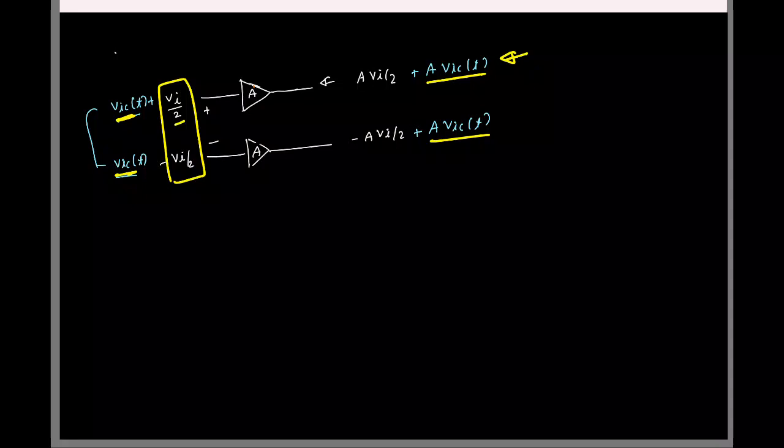Although my actual signal could be really, really small, the interfering signal is also getting amplified by the same factor, so I seem to be saturating my amplifier and I can't use it. So this implementation works properly for differential signals, but what is missing here?